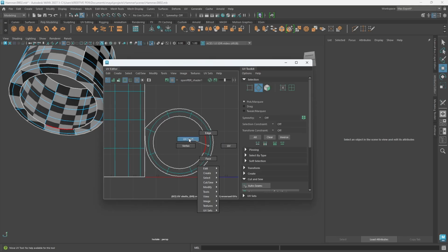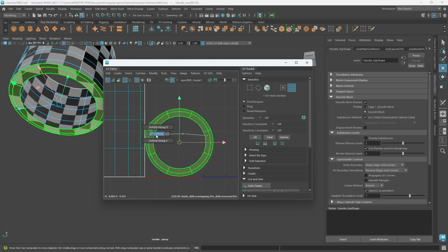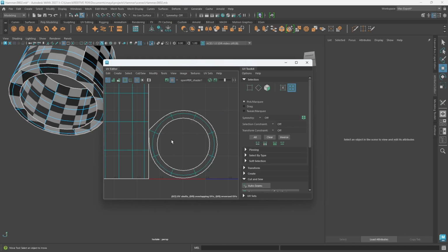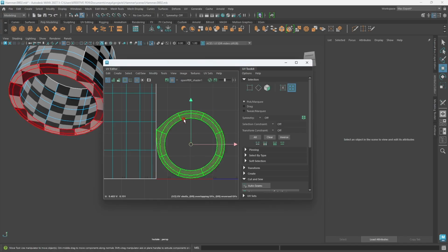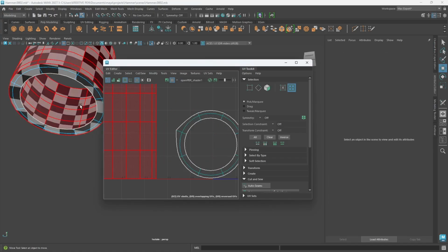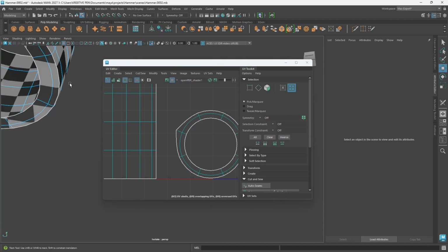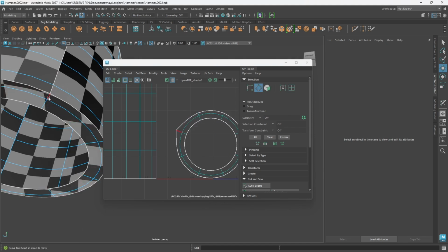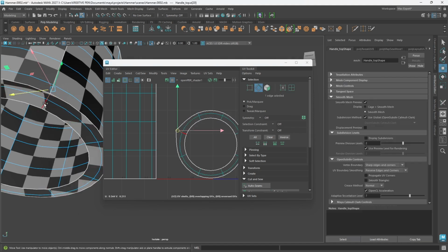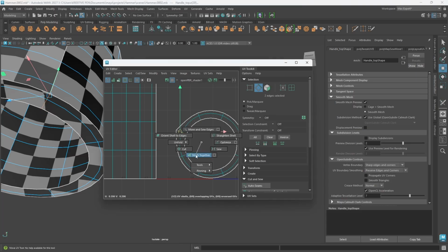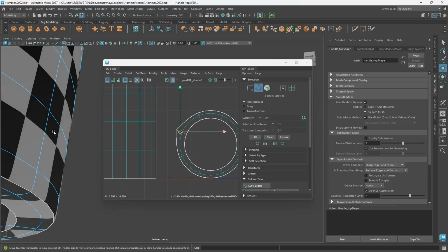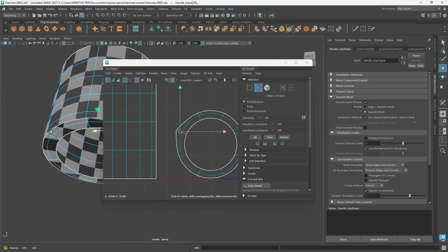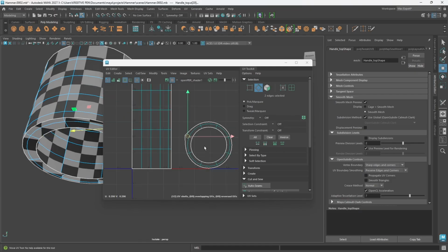So we can go back into UV shell, select it and go to unfold, and let's see, do we have any seam there? UV shell, let's shoot this out. No, we don't have any part that is cut. So let me see if we can stitch that place together. There is nothing there. It is accurate. We've already preserved edges and corners.